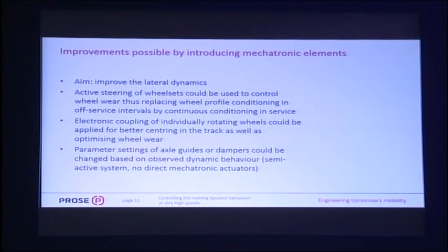Now our proposal, which goes beyond this traditional measure, is to introduce mechatronic elements. And the aim is to improve these lateral dynamics. So there could be active steering used to control the wheel wear. That means you steer your wheel set in a way that it doesn't remain in this middle position of the tread, so it wears evenly. And that could be done continuously.